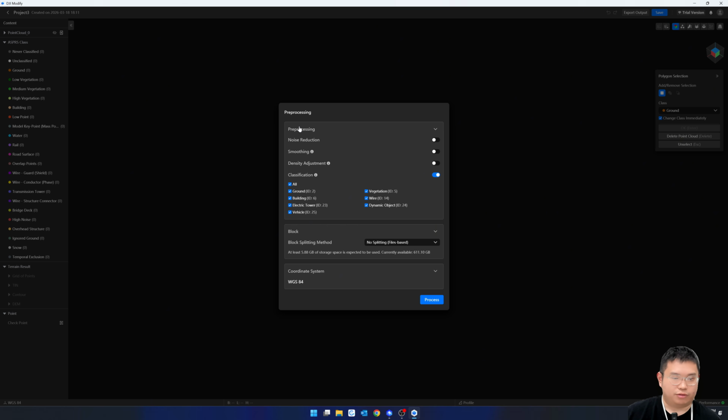And there we go. The first settings window you're going to see is the pre-processing window. These are the algorithms or processes you can apply before you start modifying the model. As you can see right now, under the pre-processing settings, we have noise reduction, which I like to have enabled because that automatically removes a lot of noise points underneath the ground for me.